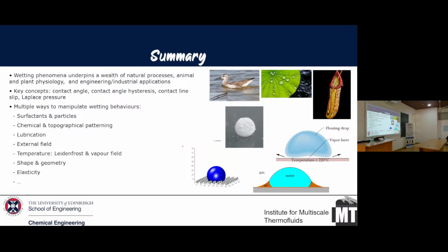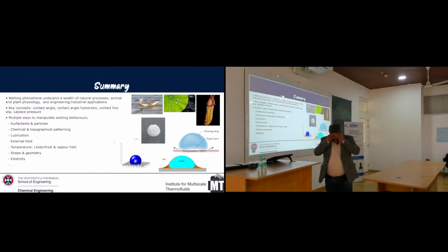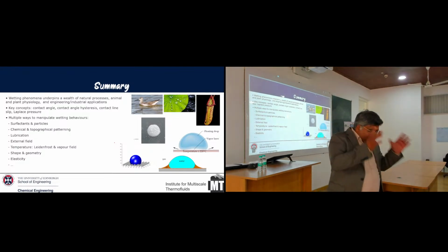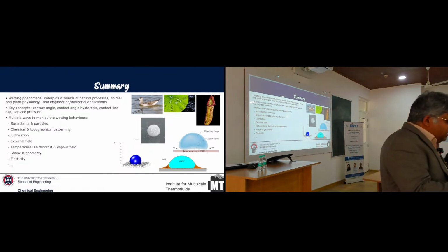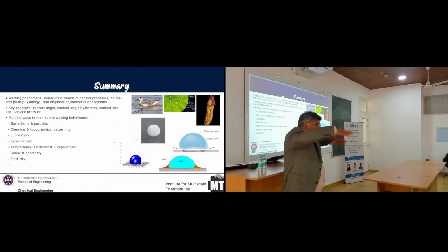Oh, very, very good question. So we found that, if it's a function of radius, I think it is, if the radius of the droplet is r, they should be less than 3r apart for them to really feel each other. But this is only for 2 droplets. If you have multiple droplets, then I don't know. Because when you have a population of droplets, they can act as a single entity as well. There's vapor shielding. I'm going to talk about that later.